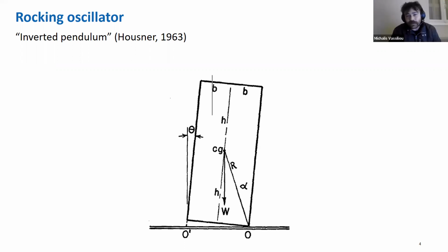But the problem is that, as you can understand, this is a wrong observation, because if you assume that the acceleration that causes overturn is the one that uplifts it, you underestimate the peak ground acceleration by a lot, because you need some acceleration to uplift this, which has to do with the slenderness. Actually, the acceleration that uplifts this is, if you do the math, g tan(alpha).